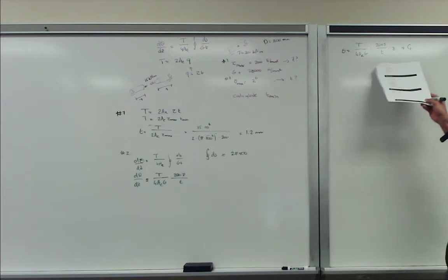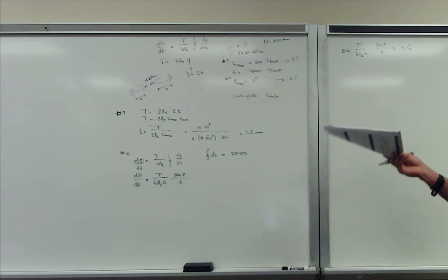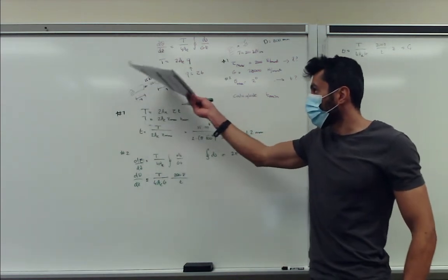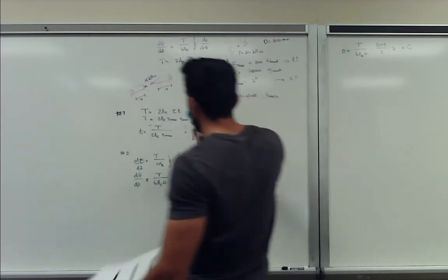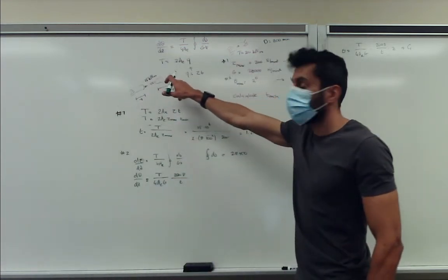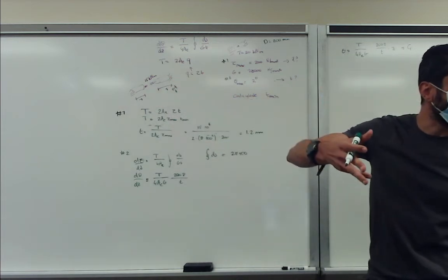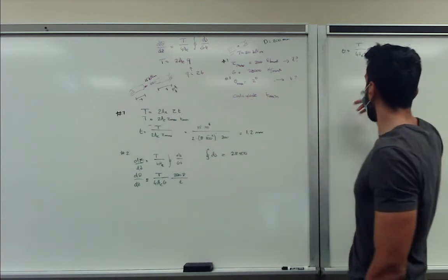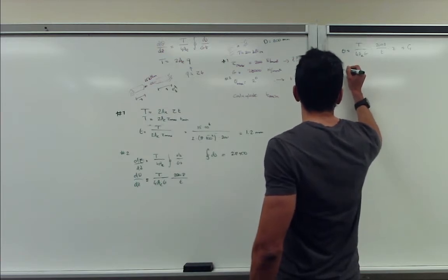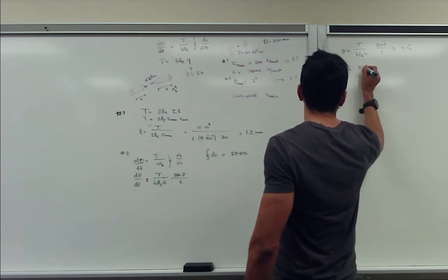So now we look back at what's this integration bound. We have to apply the boundary condition. So we apply the boundary condition in either one of the ends. Let's say that Z starts from this side. If you look at Z equal to 0, there's no rotation because it's fixed. So at Z equal to 0, theta is equal to 0.